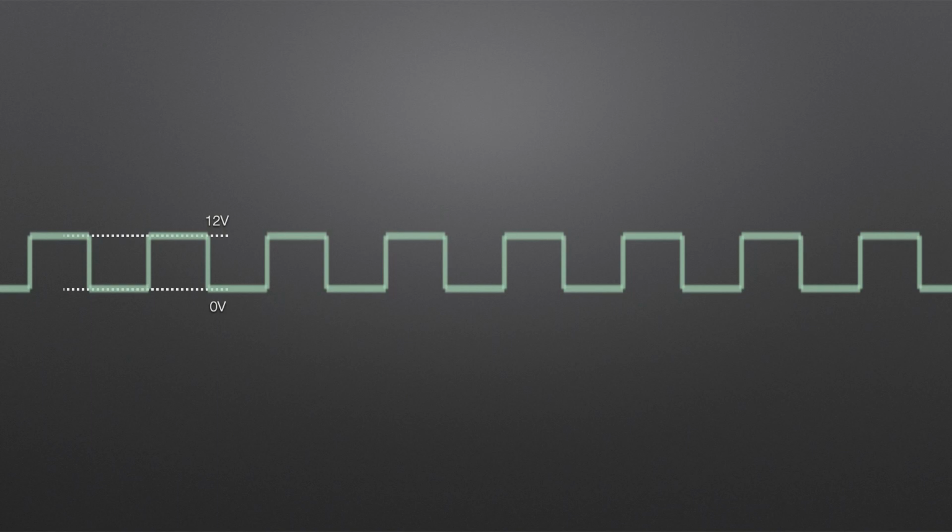The time factor is a bit more interesting as that will have a direct impact on how quick the computer operates. We want to strike a balance here where it's going quick enough to get stuff done in reasonable time, but also not so quick that it's just a blur for anybody observing the computer running. Plus we could go so fast that we exceed the speed the relays can actually operate at.